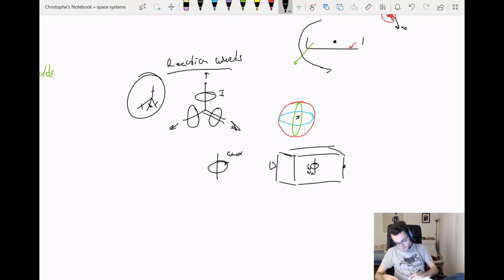Say you have some thrusters on board. Well, hey, that's convenient. We can spin up in the direction that we want to keep spinning while slowing down the reaction wheel, such that the changes in our angular velocity remain constant. So we're not actually speeding up along our axis, we're not slowing down, we're using the thrusters to compensate for our angular velocity decrease from slowing down the reaction wheel.